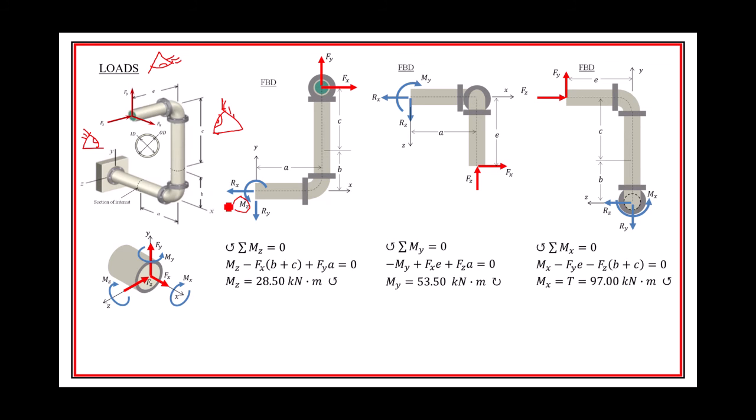What we've essentially done is moved these forces from where they're located here down to this section. And in the act of moving, we've shown that they have these moments. And all these moment directions are opposite from what we got from the FBD.